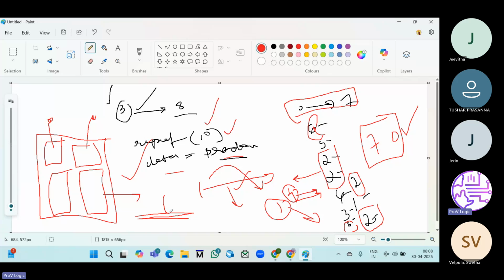In SystemVerilog we use the interface block, where we connect design and test bench with respect to clocking blocks and modports, so that everything is connected dynamically and we can access it through objects and instances.